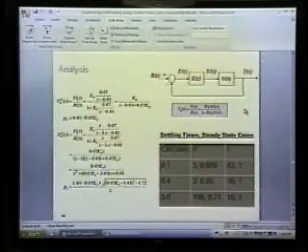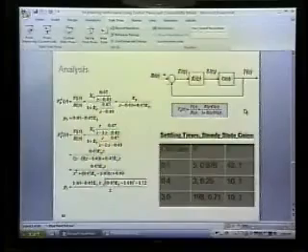If you've got multiple control parameters, you need other kinds of techniques, and there's something called root locus analysis, which was basically a graphical technique that was developed over a period of time. It's very effective at giving you some insights in terms of these trade-offs. There are also numerical techniques you can use for two, possibly three parameters. Yeah?